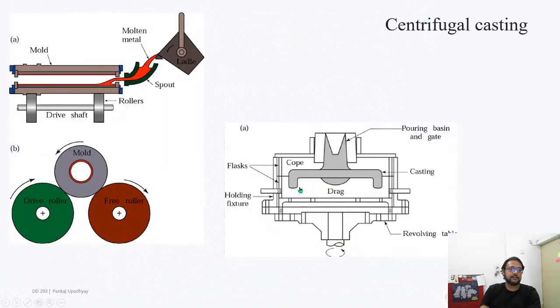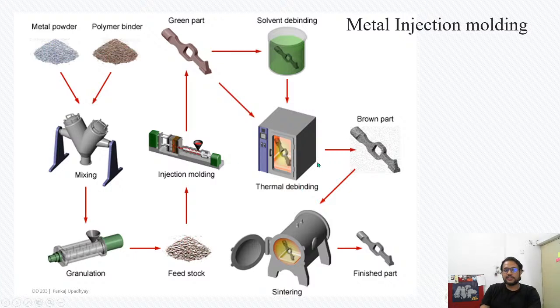Okay, and right, so this is metal injection molding, and it's really used a lot in medical engineering applications where you want very small precision parts, and it's used extensively there. However, just because of the number of steps required and the complications of using an injection molding machine with metal parts and all that, it makes it slightly expensive. Okay, yeah, so this is metal injection molding.